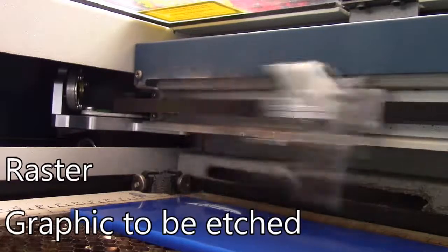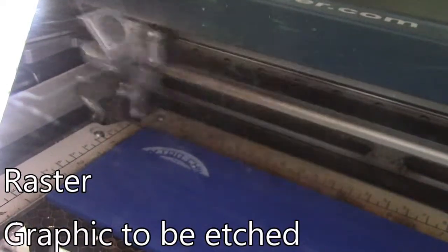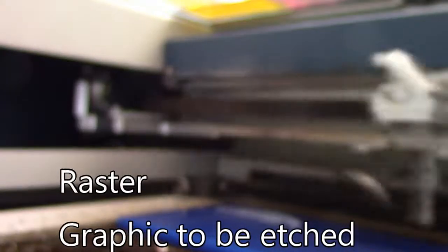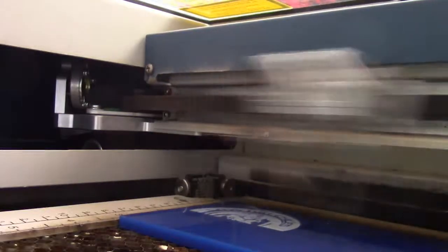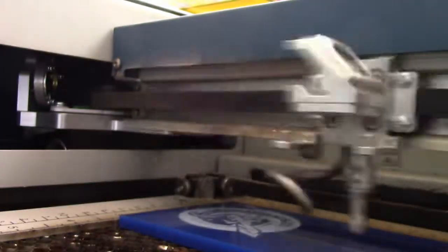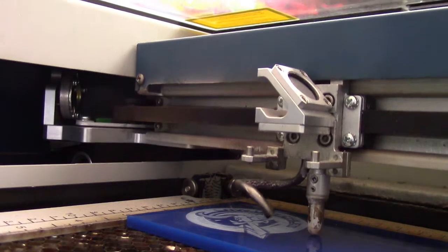Here, like I said before, it's rastering, or burning, that image onto the material. Notice that the laser is moving very quickly from left to right as it slowly moves down. This allows it to etch the design perfectly as we put it in the program. After it's done rastering, it's going to vector, or cut, the circle on the perimeter so that I can remove it from the sheet.